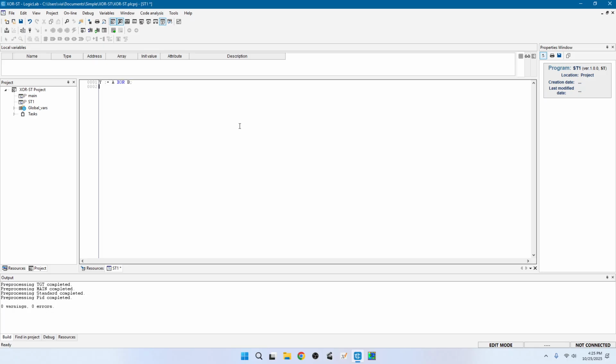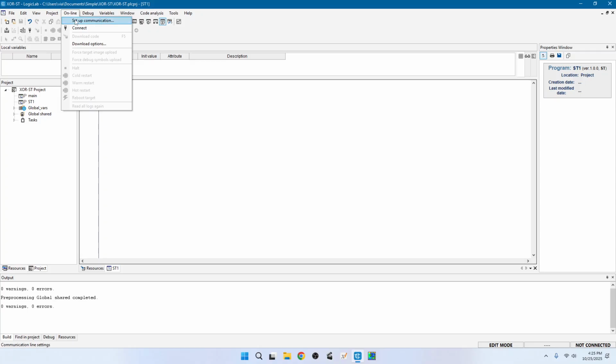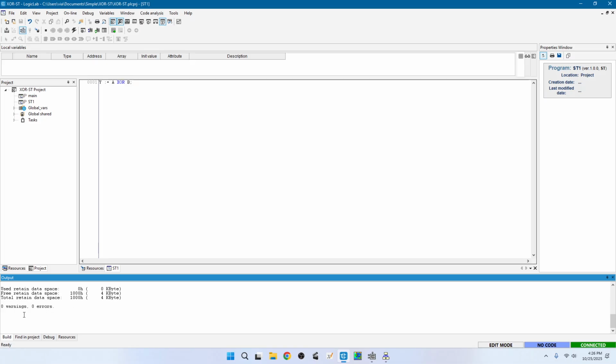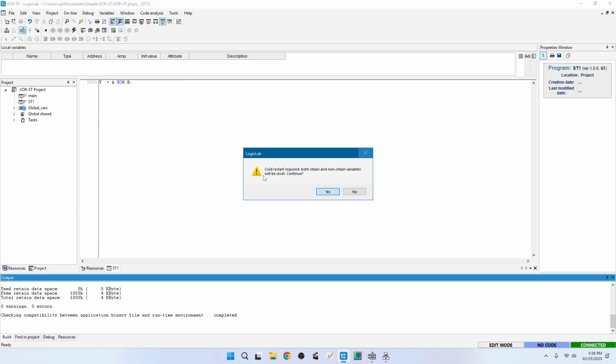And you can see if you do more lines there, in this case would just be blank lines. So that's our program. All right, let's save everything and go online. Debug simulation mode, and then project, F7, no warnings, then online, download code.